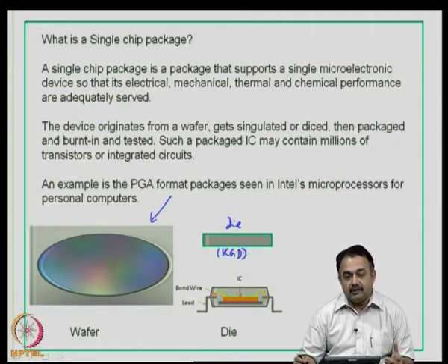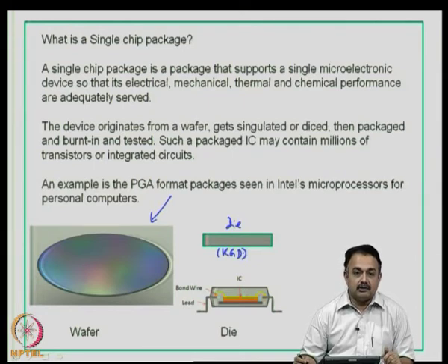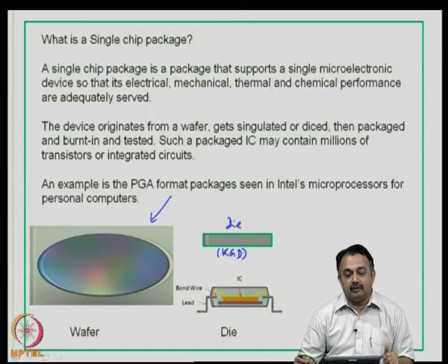we are going to look at what format or form this particular microprocessor die is going to be available in the market, whether it is going to be in the form of a lead or a pin or a solder ball. Normally for microprocessors it is going to be packaged, but for other prototyping applications this packaging sometimes may not be done. So, it can directly be mounted onto your second level system, which is the printed wiring board. That is known as a bare die. The conditions for using a bare die and a packaged die depend on the application that you are going to work with.